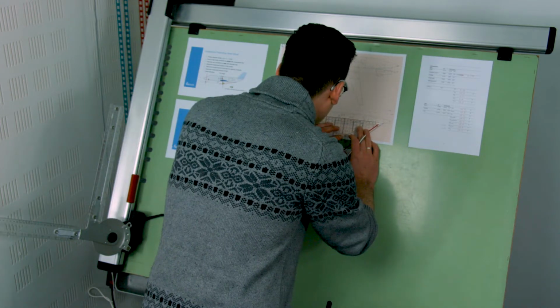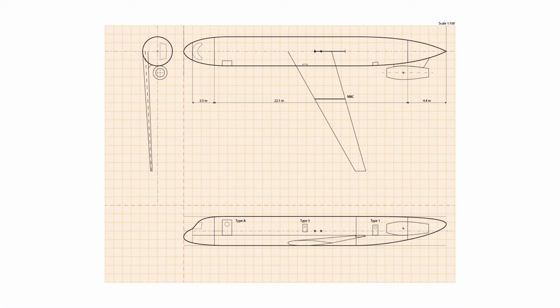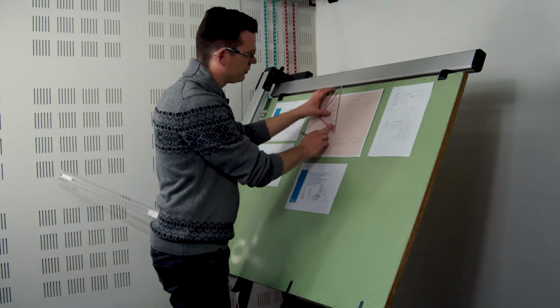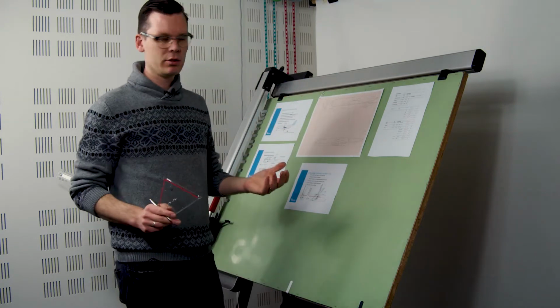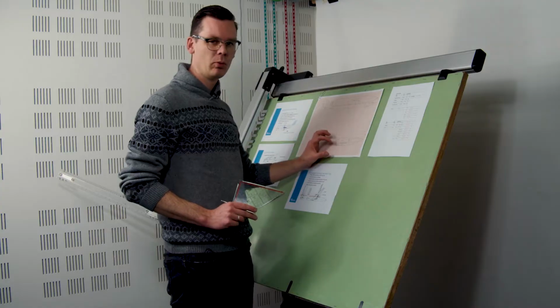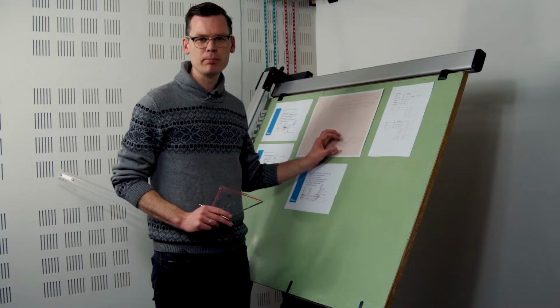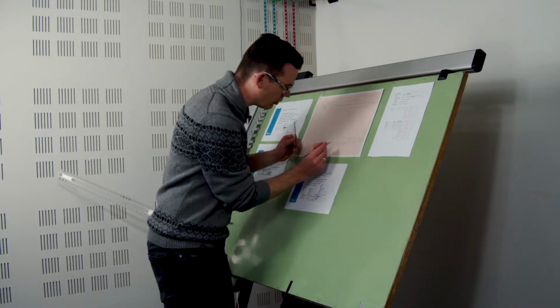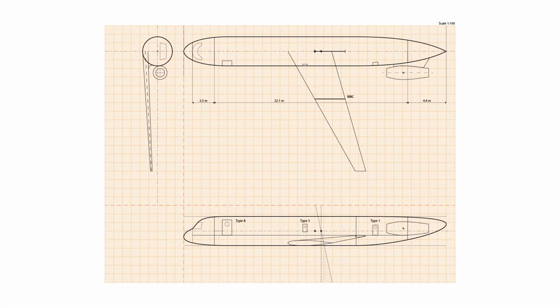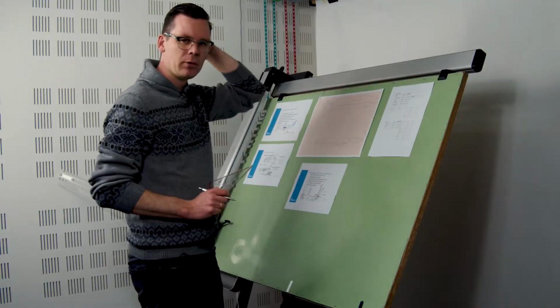So I actually draw a line through the aft CG at 12 degrees. That is going to be a line indicating a boundary or a constraint. So the wheel axle should always be behind that line. I can indicate that with these hash marks there. Now the next thing I'm going to do is